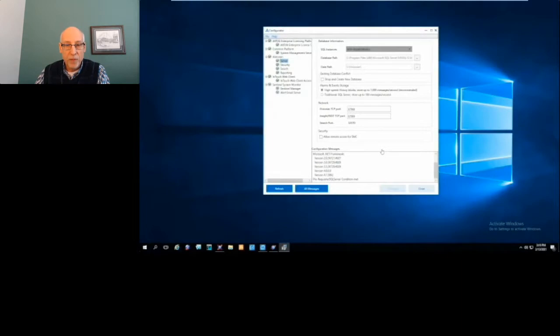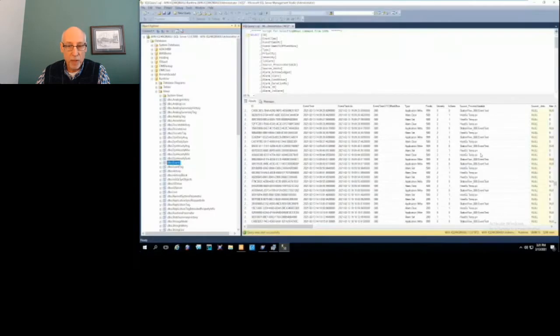One of the more recent features we have with System Platform is the ability to store the alarm information, the alarm history, into the AVEVA Historian history blocks. If we go into the configurator, this is where we configure that. We tell it we want to use the high-speed history blocks to store the data. And that gives us the ability to see that trend data, or the alarms overlaid on top of the trends, and to pass that information up to Online Insight. So it's a great use case for the alarm information: store that in the Wonderware Historian, and then do some correlation between the Historian trends and the history blocks.